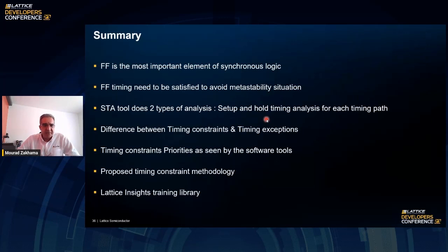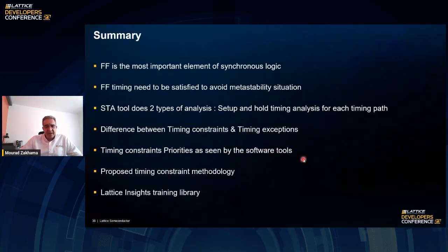We looked at the difference between timing constraints and timing exceptions, the timing constraint priority seen by the software tools, and the different ways of resolving priorities associated with the timing constraints or timing exceptions. And we proposed a timing constraint methodology to get to timing closure. And obviously, don't forget about the Lattice Insights training library, where you can find a lot more information about all these topics and more